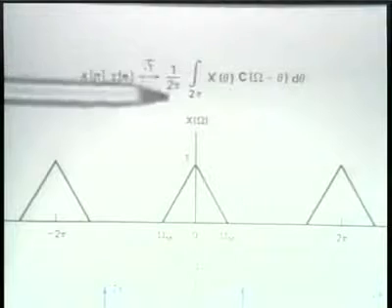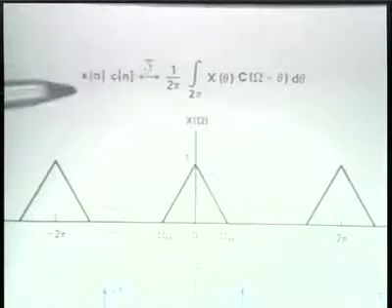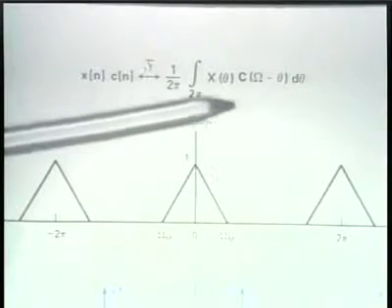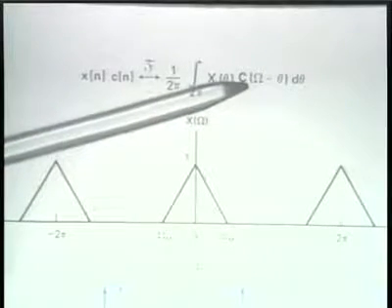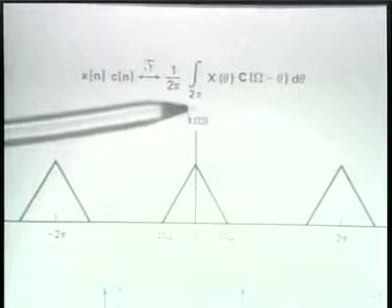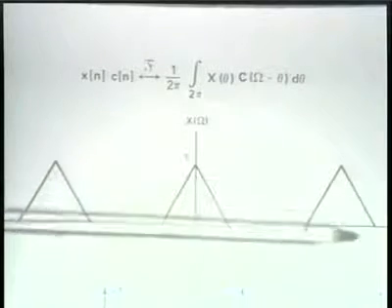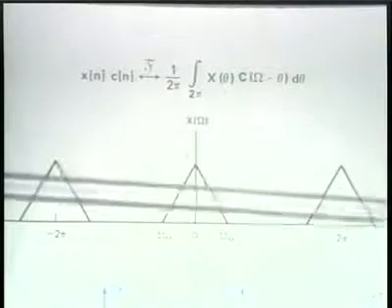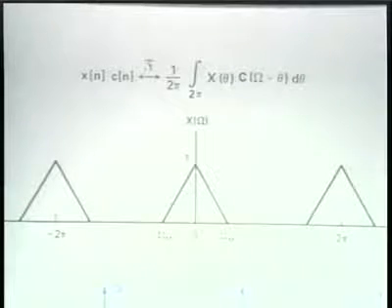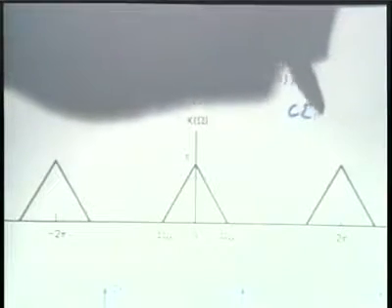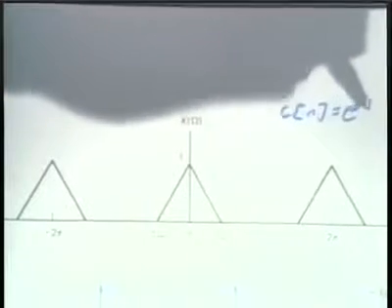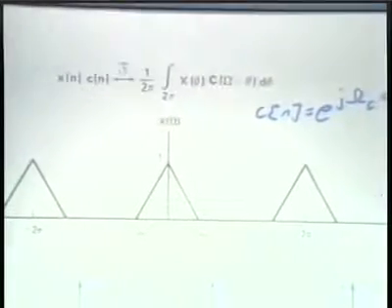And the modulation property tells us that the spectrum of the modulated signal is the periodic convolution of the two spectra. Let's consider, for example, an input or modulating spectrum, as I've indicated here. And since we want to consider, first of all, a complex exponential carrier, we'll consider the case of c of n equal to e to the j omega sub c n.